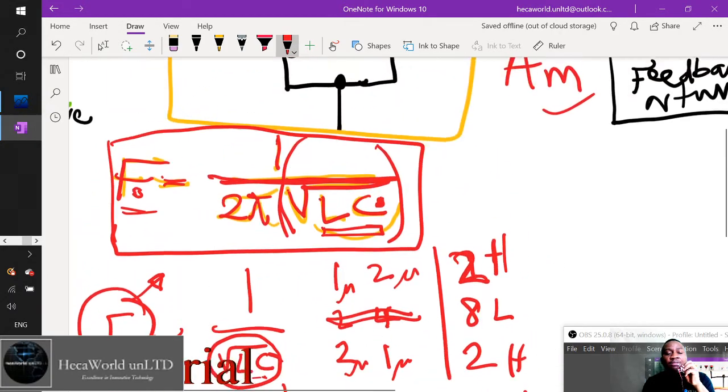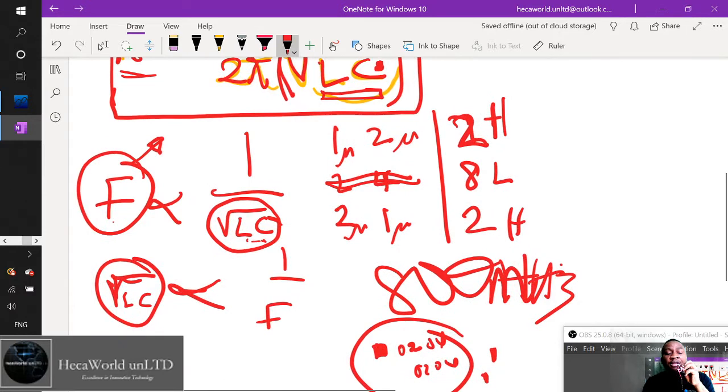Alright, so I think that will be it. Remember again today, when we pressed the inductors tight, the frequencies were decreasing. So which means we're increasing the inductance as we pack them together. As we spread them out, the frequencies were increasing. So when we're spreading them out, we're reducing the inductance, and the frequency is increasing, right?